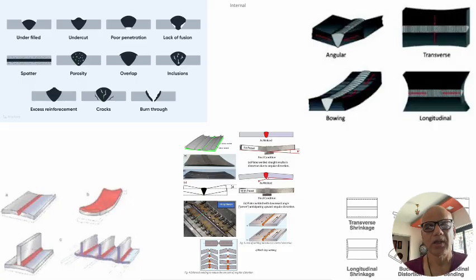Or if you want really a wider width, you should weave it and have a dwell. The dwelling in weaving is very essential. Dwelling is you wait, stop at both the ends of the width which you are covering, and then deposit, allow that dwell, that is the wait period, to deposit more material there and improve the profile.